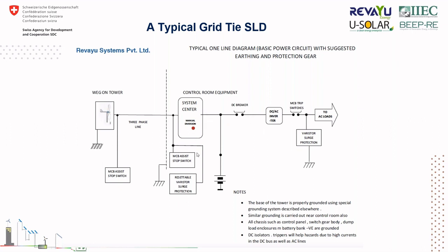The surplus power goes to the dump, and this goes into the grid tie inverter, or we have a battery over here. We have to choose as per the system design whether it will be an inverter or a battery. For both, there is a slight difference in the settings. When we discuss with the client, we finalize, and accordingly the controllers are configured in the factory settings.